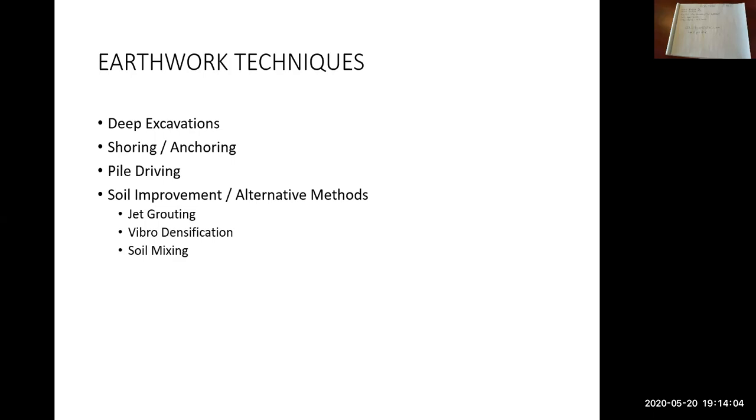Again, they're used for various purposes. Increase the density of the ground. That's probably the biggest one. Prevent water from entering an excavation. Yeah, those are probably the two biggest purposes. Again, if you increase the density of the ground, that means heavier loads can be imposed on that ground, meaning a new building could be built there, for example.